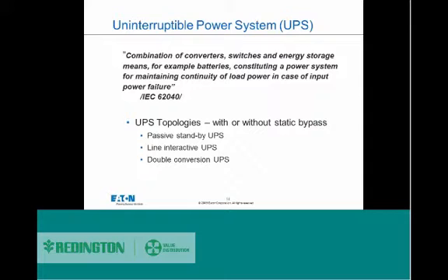If you're already in the power industry or have been selling UPSs and power solutions to your customers, you would ideally get questions saying we want a line interactive UPS model or a double conversion UPS model, apart from what power rating the customer is looking for.